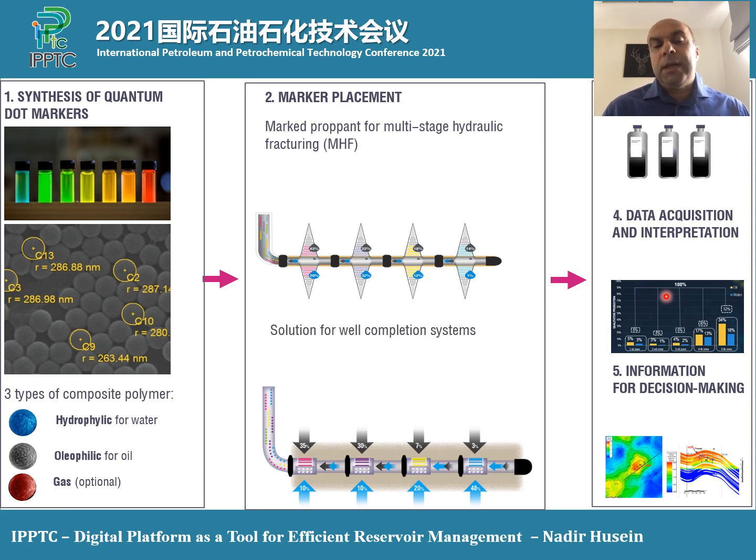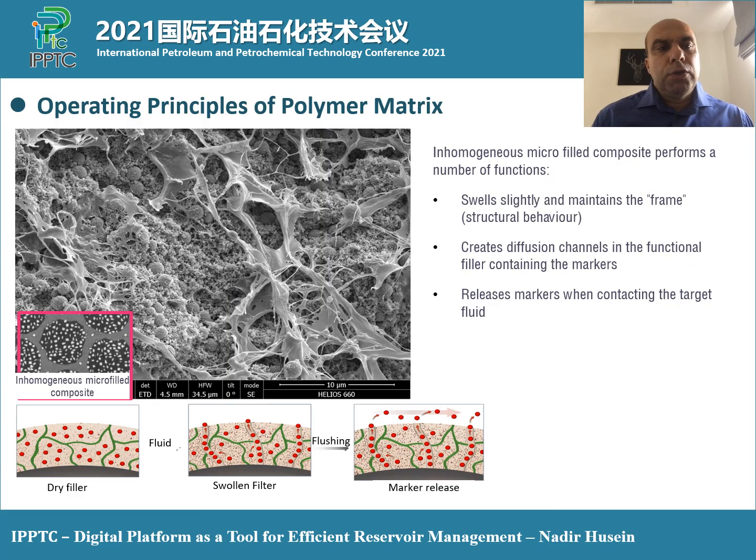The technology that's used to analyze the traces in this fluid sample is called flow cytometry, adopted from biotech. And the advantage of this technology is the fact that there is no need to shut in the well during the sampling period, and it still gives ability to do the quantitative analysis of zonal contribution and phase contribution to the total production rate.